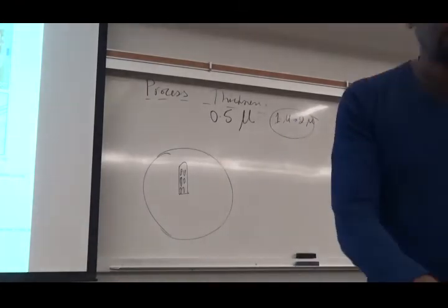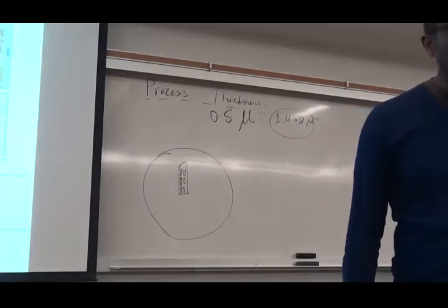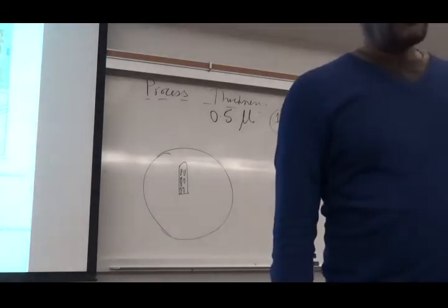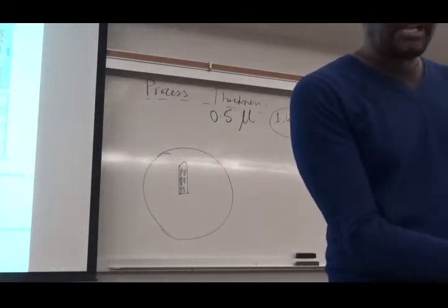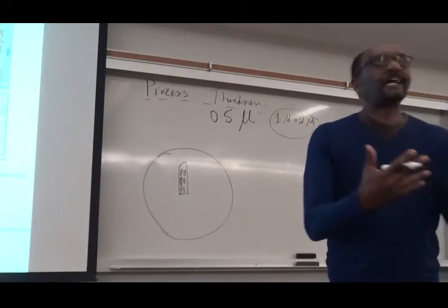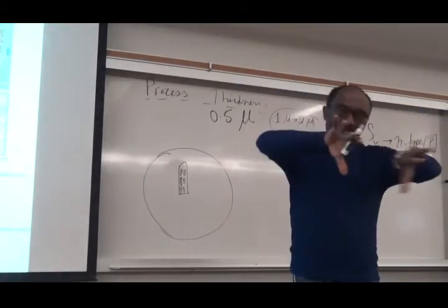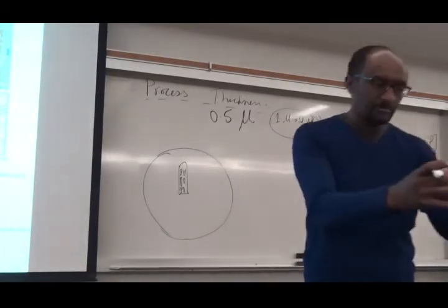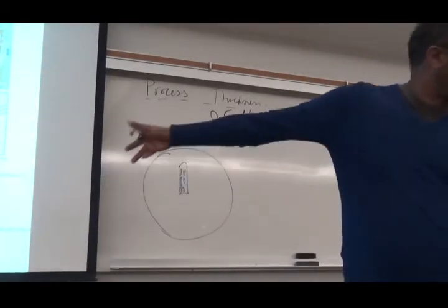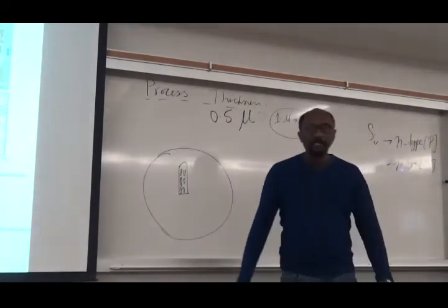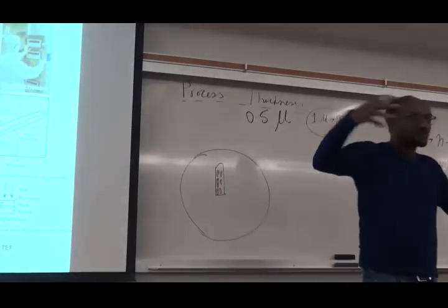But it doesn't actually have like a legitimate opening. It's still clear, right? Like there's still, yeah, it's clear, but of course at the bottom you have silicon. Yeah, I understand. So the silicon part is what I want to be doped. So essentially I'm protecting every part I don't want to be doped and then exposing that part. And that's the beauty with the photoresist. Okay? That's the whole idea why I'm doing this patterning.